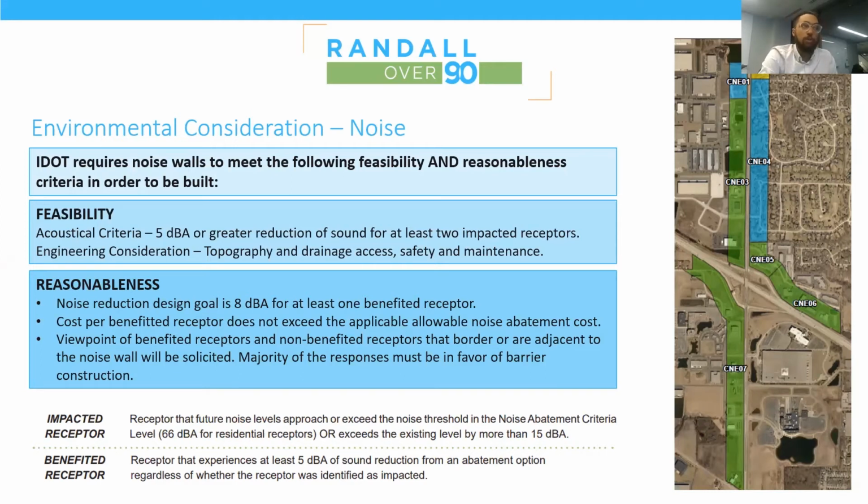Once you've calibrated your model and you think it's accurate for the area you're modeling, you then input the maximum traffic counts into that model, and the model will then output the sound level. So it's not quite a constant sound level, but it's an averaged sound level over, I believe, an hourly average.